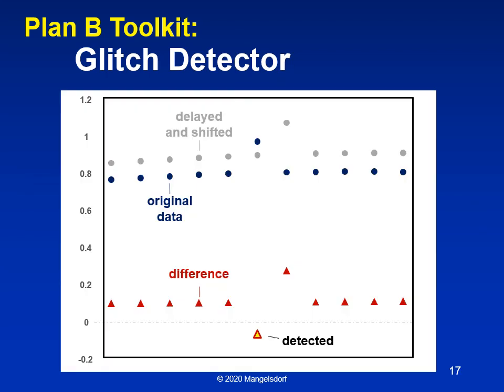This shows an example of the glitch detector at work. The first thing you should notice is that you want to set it up so that you alias the waveform down to a very low frequency, so the signal component doesn't really cause the output to change much from sample to sample. So you're aliasing almost down to DC. The derivative in this decimated data is very, very low, and if everything's working right, the only deviation should be thermal noise.